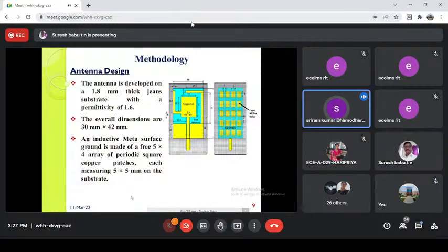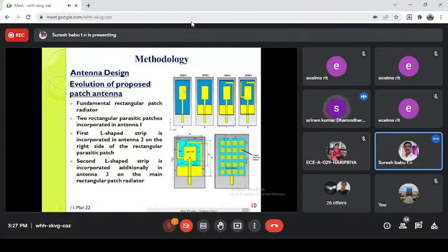For this geometry, for example, how did you calculate the dimensions? Sir, first of all, I start with the first patch, 15 by 17. The lower geometry, you have some dimensions, right? The numerical values, 12.5, 13.5. How did you calculate? Using the transmission line model, sir, with the width and length formulas. How about the feed? What type of feed is shown here? Here I use a coaxial feed, sir. Any reason to go for coaxial? The fabrication is simple, sir, compared to others.